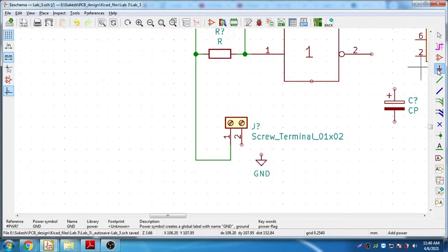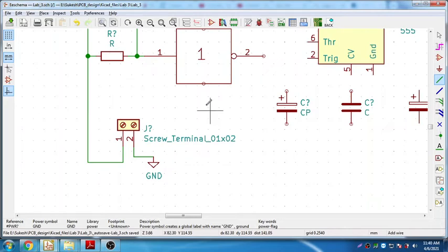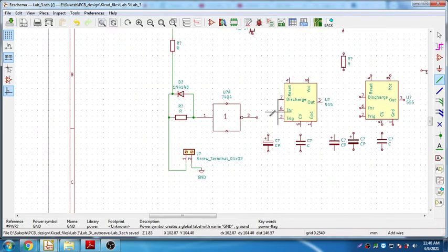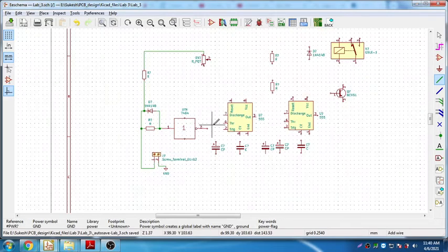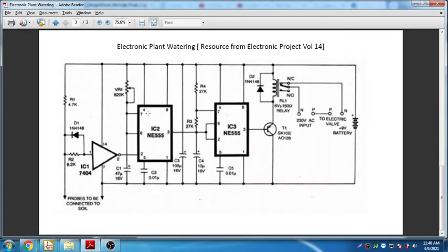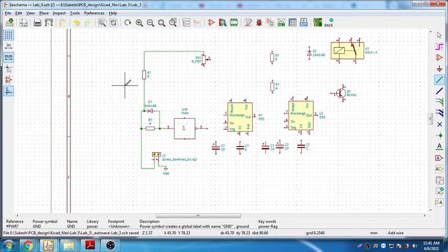So this is connected to the ground. Okay. So I connected this to the ground. Now this part of the circuit is complete. So let's connect to this side. What all we need to do: pin number 6, and if you look at the circuit, pin number 6 and 7 are shorted. Pin 2 is supposed to be given to the inverter, from here to the port. Okay, so we will do that connection.